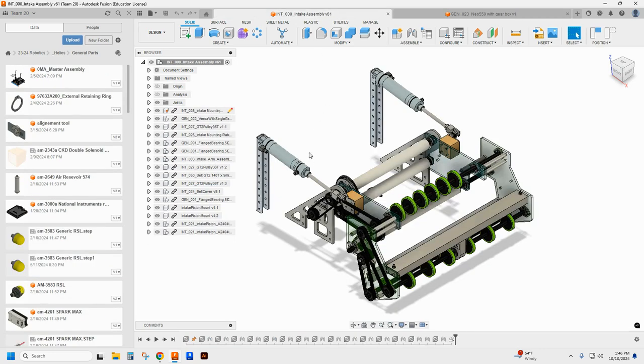So when you're working in an assembly, avoid creating new components within that assembly because somebody's going to try to refer to it, create a drawing from it, use it in another subassembly, anything like that, and it's going to get really confusing really fast because it's not in our folders and it's buried deep down in an assembly somewhere.